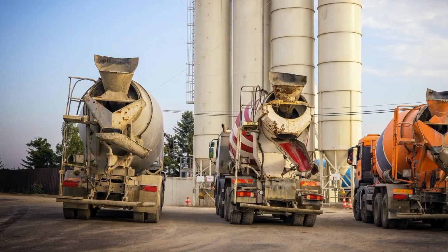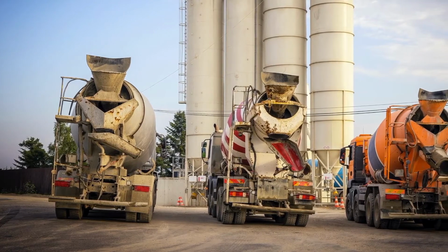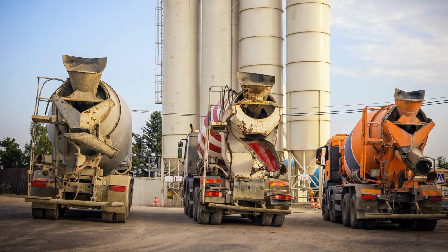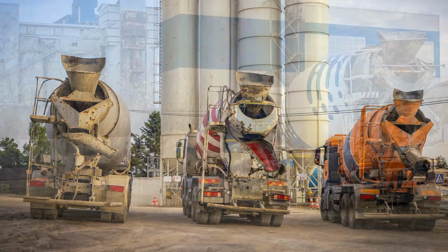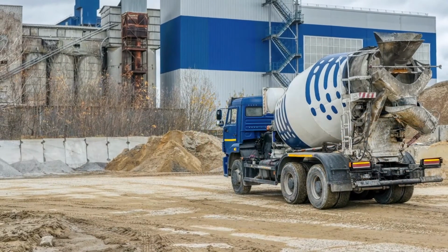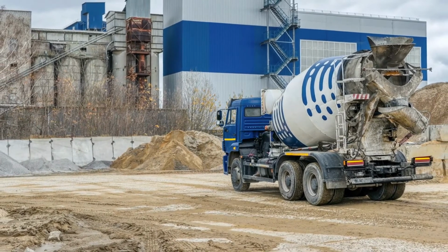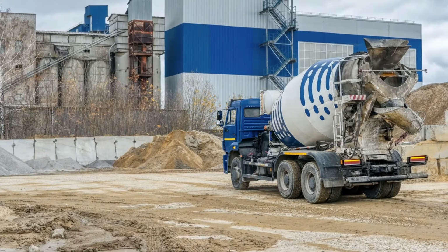Lower overdesign means lower cementitious materials content. For example, going from 1200 psi to 600 psi overdesign would likely require 60 pounds less cementitious material, potentially an 8% decrease in embodied CO2.